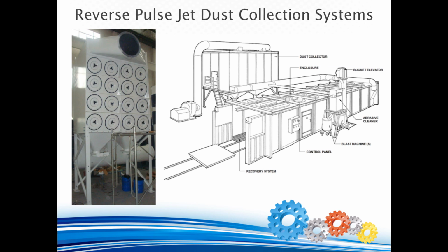Add 10% to the required flow rate if the blast room system will be used by more than one blast operator. It is also important to note that single-use expendable abrasive media such as copper slag, crushed glass or silica sand should never be used in a blast room system due to dust overloading from the high abrasive breakdown rates.